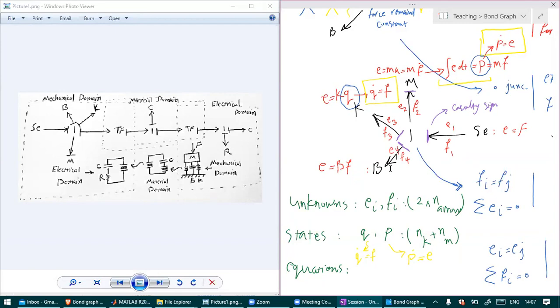And if you define a system where causality is not satisfied, you end up with a singular system. In terms of control design, for example, the inverse is diverging. In hydraulic systems, that's important because that causes a lot of vibrations. So the causality helps understanding if a system is physically feasible or not, if the system is fully defined or if it becomes singular at one point. That's the point of it.